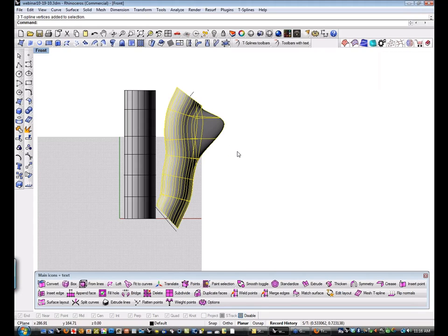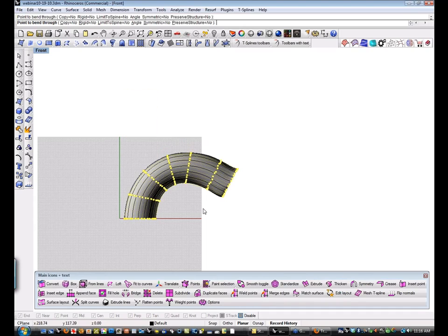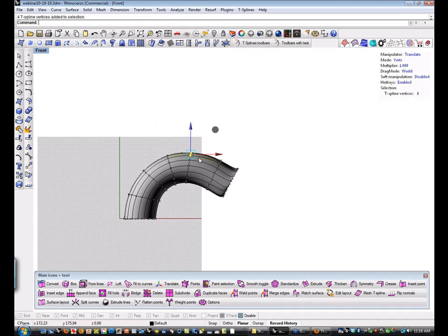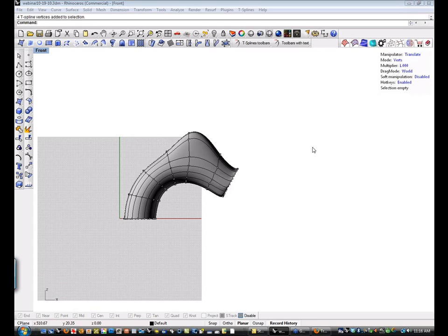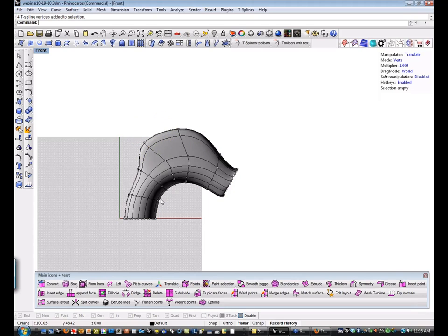That's kind of the rule with all the UDTs. If you want to use any of the UDTs, like say for instance you wanted to use the bend tool, I use this one a lot. Do it on the points. Grab bend, and it stays T-splines. I use that all the time. I love the UDTs. I love them. I use them all the time, and the fact that you can use them on T-splines objects is even awesomer, if that's even a word.